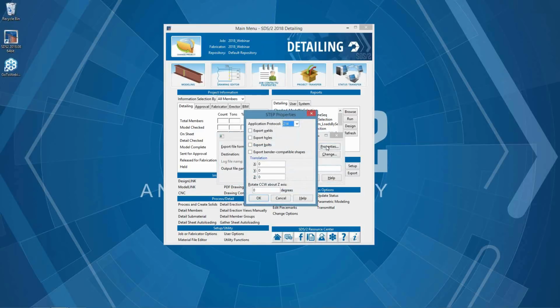Under the properties, you will find that the default application protocol is 214. This AP exports submaterial colors, but the AP 203 does not. So you have the option for AP 214 and AP 203. Just like other exports, there are options such as export welds, export holes, export bolts, export bender compatible shapes.